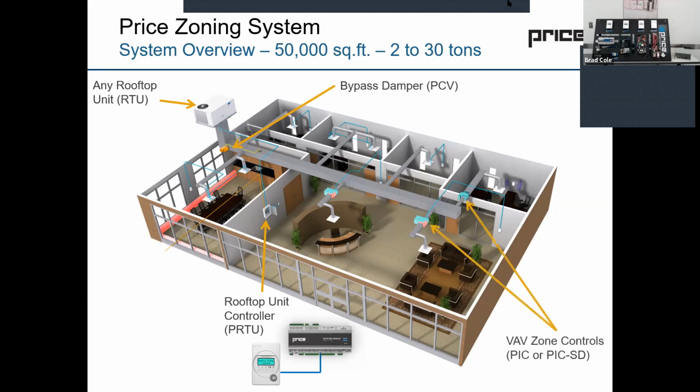As we get into the open spaces, we might look at designing in, whether it's an engineered or a design-build job, a single duct or maybe a fan powered box with reheat, and we can use the VAV controller to control those types of applications and sequences, no problem. In the office spaces that we put into these buildings, the Prodigy diffuser was commonly used.